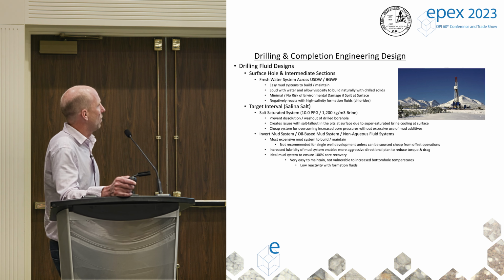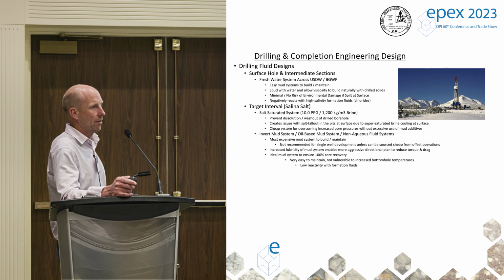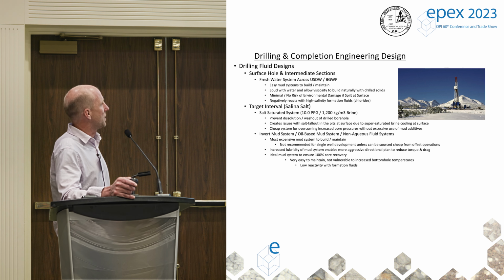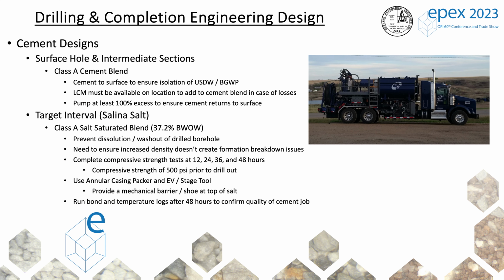One benefit we saw with the invert systems is in our core recovery. Anytime we're taking cores, the invert system helps guarantee we're going to get 100% core recovery. But for the most part, if we're not coring, we're using a salt-saturated brine system.